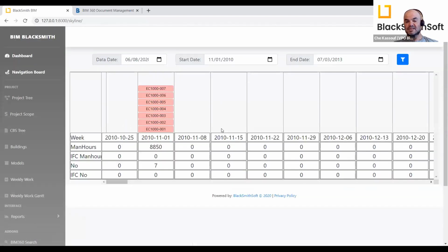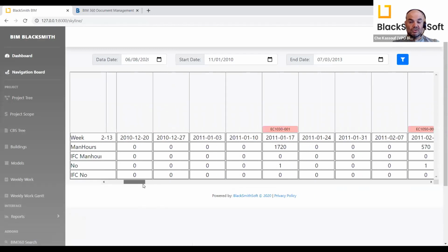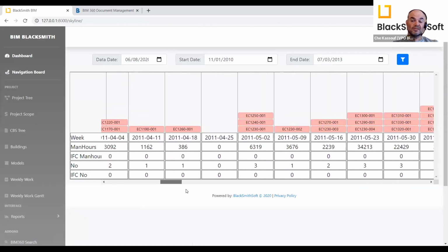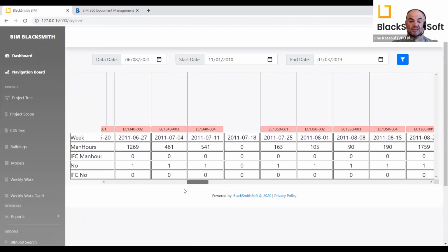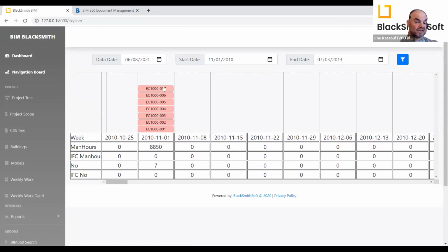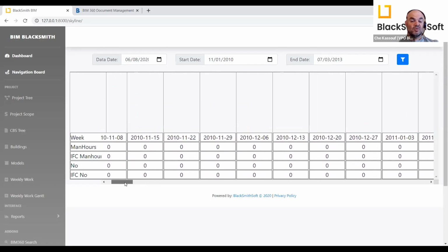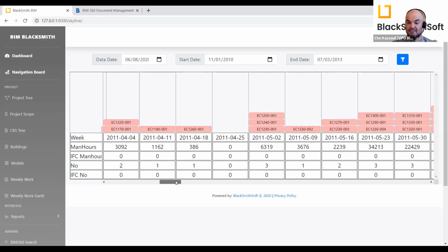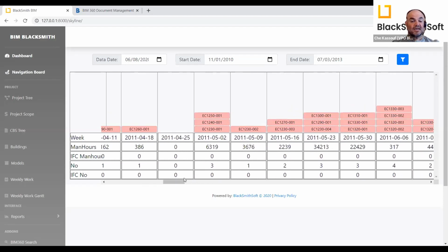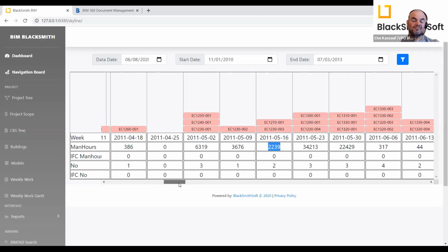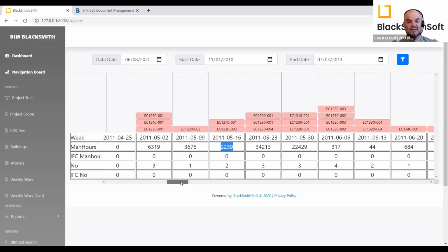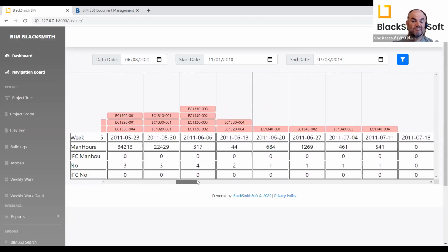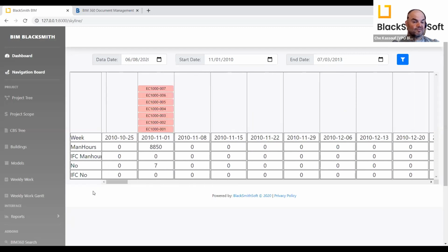The other report I want to show is what we call Skyline. This Skyline, for example, is a report that we have borrowed from the oil and gas industry. You can see here, it will give me a good idea whether my plan makes sense or not. You can see this guy started with so many activities in here, then he waited maybe 2 or 3 months to start a certain job. Definitely, this is not a good plan. A good plan will mean that these numbers here, the man hours assigned here, should be homogeneous, and they follow a certain bell shape form, of course.